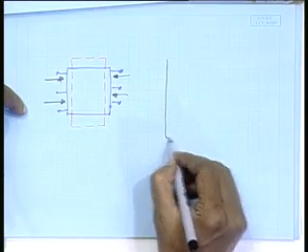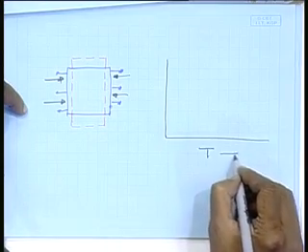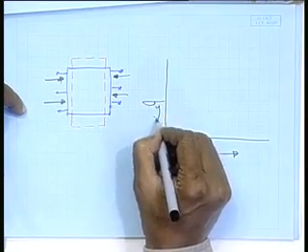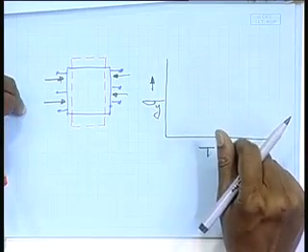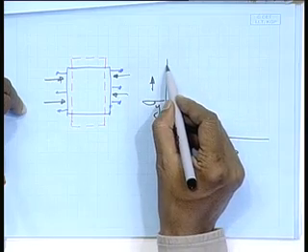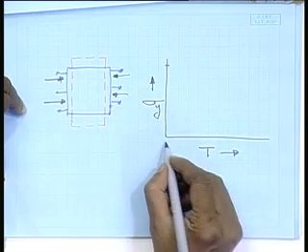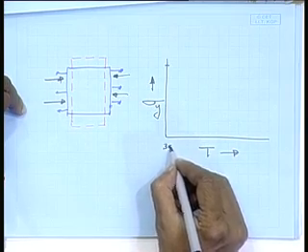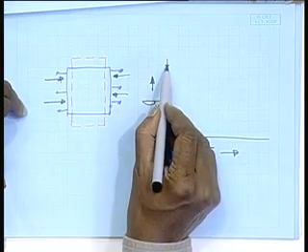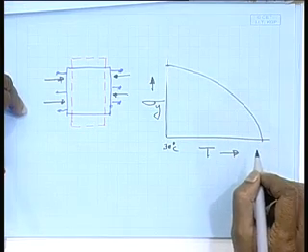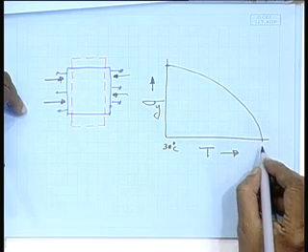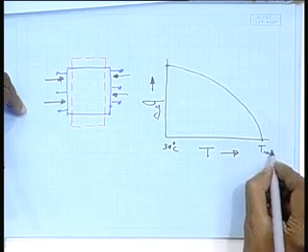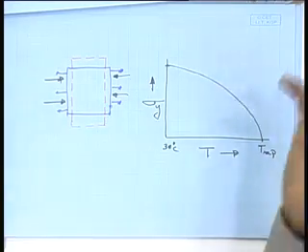So, I know the stress and temperature distribution. Yield stress is a function of temperature. This is my yield stress at room temperature, say this is 30 degrees centigrade. It drops like this and becomes zero where? At the melting temperature. When the metal is liquid, obviously it cannot take any stress, it flows, isn't it?